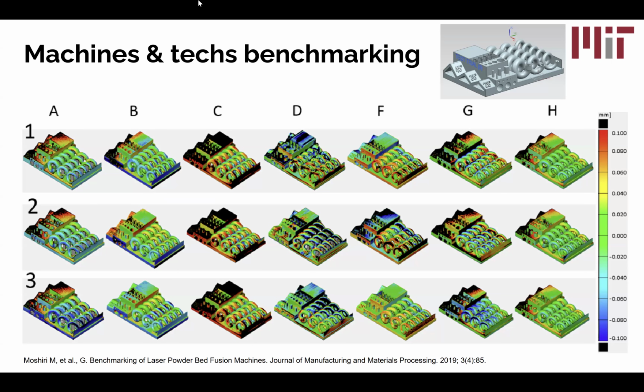And then the second question you should ask if you're buying parts, not machines, but parts specifically, is after you get a benchmark that you're happy with, right? Ask them, hey, who's printing these parts for my production run? Is it the same person in the same machine that made this really good benchmark? And if the answer is no, because sometimes the answer is no, right? You might want to re-benchmark based on the actual production partner.